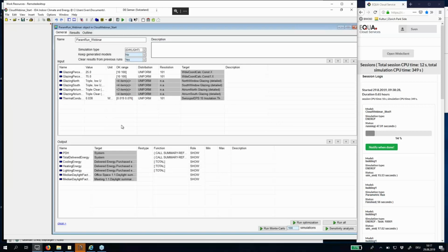For instance, you want to change the U value of an external wall with a single parameter. But in the model you have the conductivity of every layer of every wall type as a separate parameter. So you want to define 1 parameter that influences all the other parameters, and you can do that in different ways. One way is to use a resource, and I want to show you how you can do this.